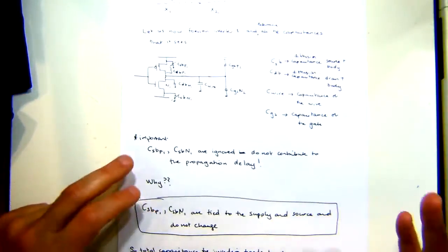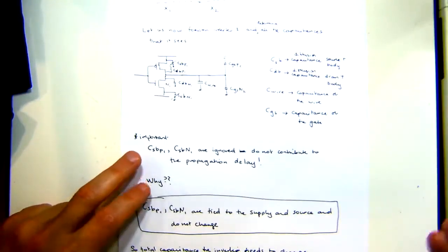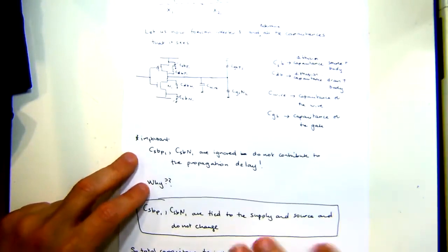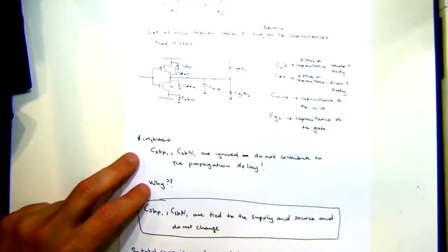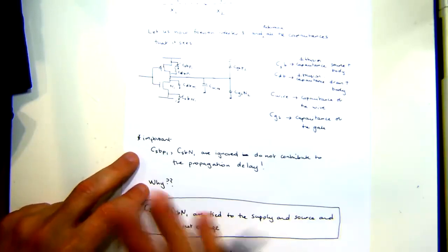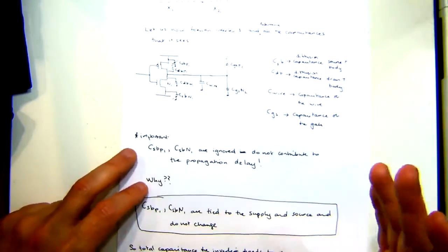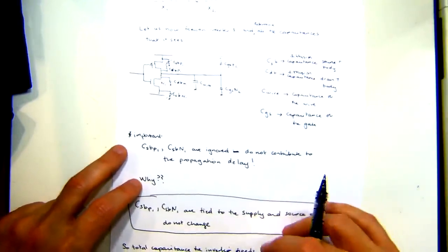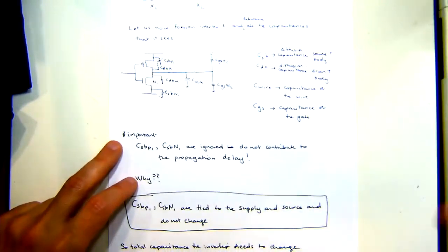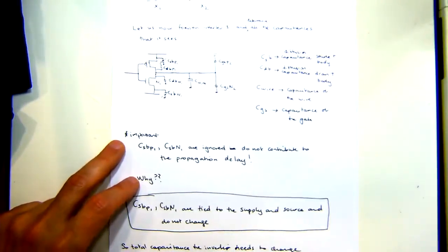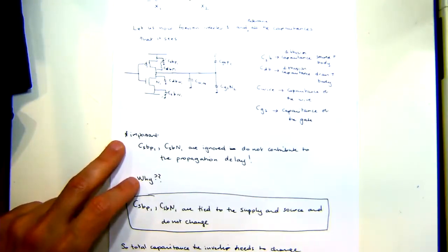Now, the problem is, if you increase the distance on a chip, you have to go through multiple vias, and then you've got to worry that the vias are sufficiently large so that you don't add a ton of inductance. And the other problem you face, at least on the chip, is that as you go higher in layer, especially in the back end of line layers, the minimum feature size becomes quite large.